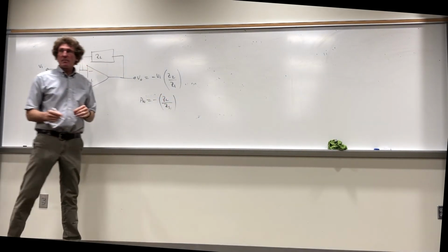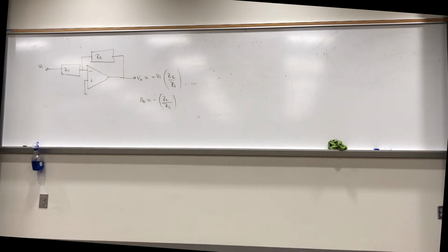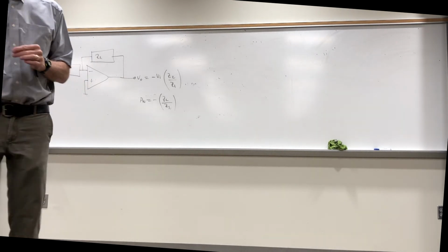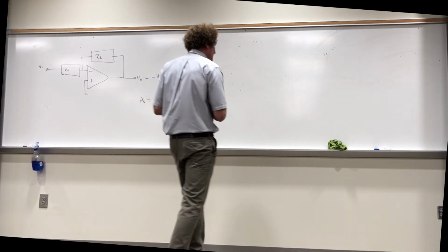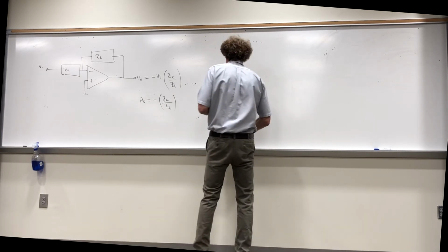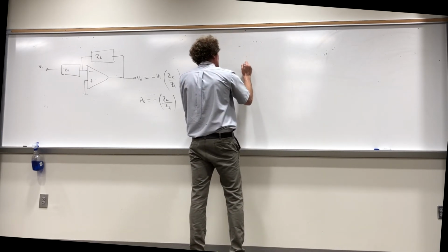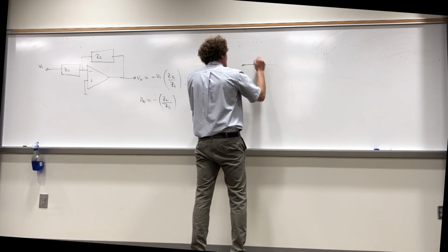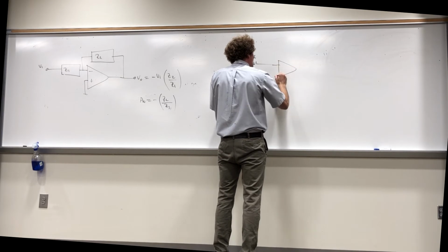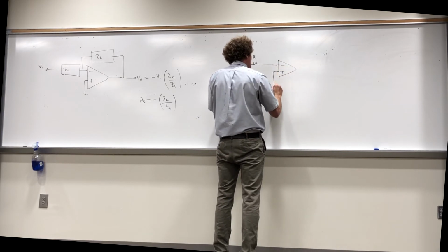Now we're going to talk about how you realize the 1 over S. Most of you by now probably see this. But you saw a lot of terms where there was 1 over S, right? When I drew those block diagrams, I had 1 over S, 1 over S. Some of you see it very easily, some of you don't. Now, what happens if I have this? I'm going to go ahead and put a resistor, simply R here, goes into the negative terminal of an op amp, that's positive.